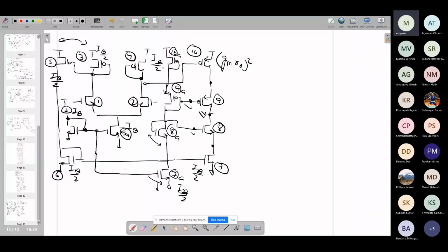So here we are looking at these MOSFETs, and the same current is flowing in these two branches. We are establishing the VGS with the help of this bias branch. Whatever VGS is required to support that current in M8 and M9, we are creating similar VGS, similar gate voltages, by pushing the same current in this bias branch, and then using those gate voltages for biasing the output device, output branch. That's all. And then your output is anyway being taken at this particular point. So that is all we have to do for appropriate bias point of the Cascode devices.